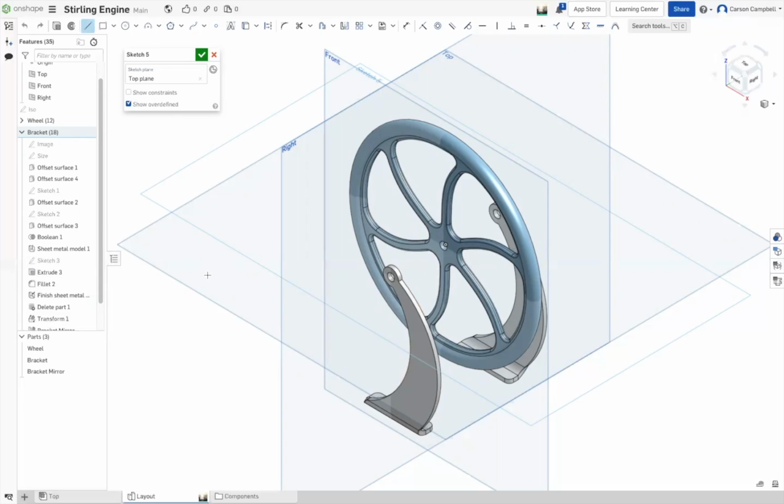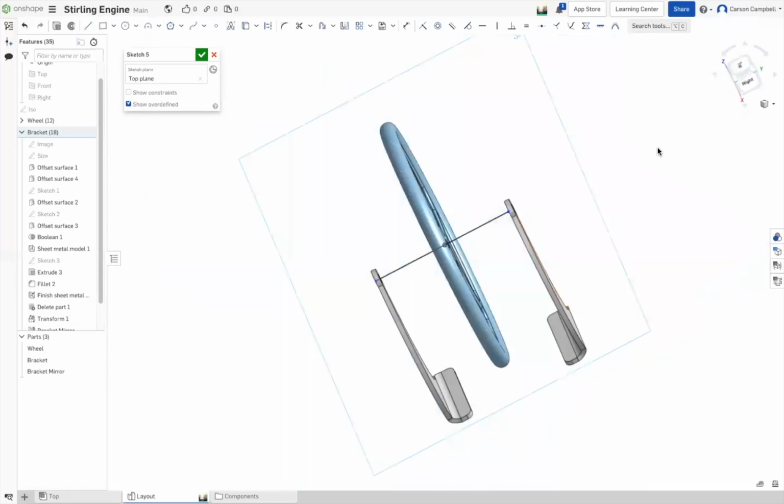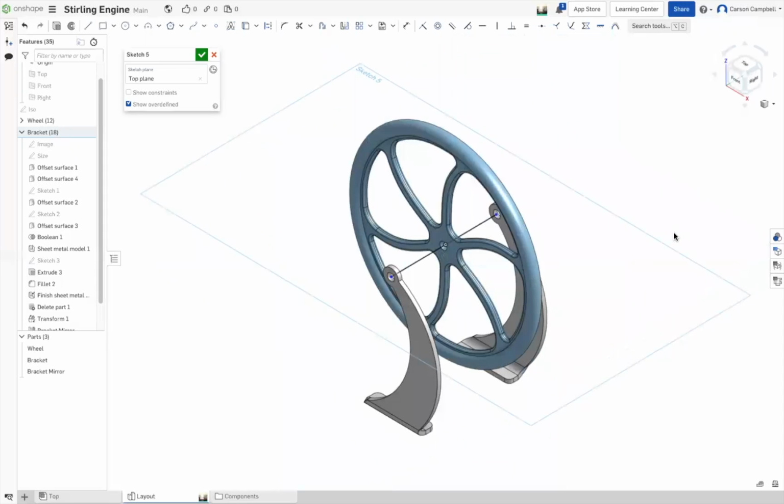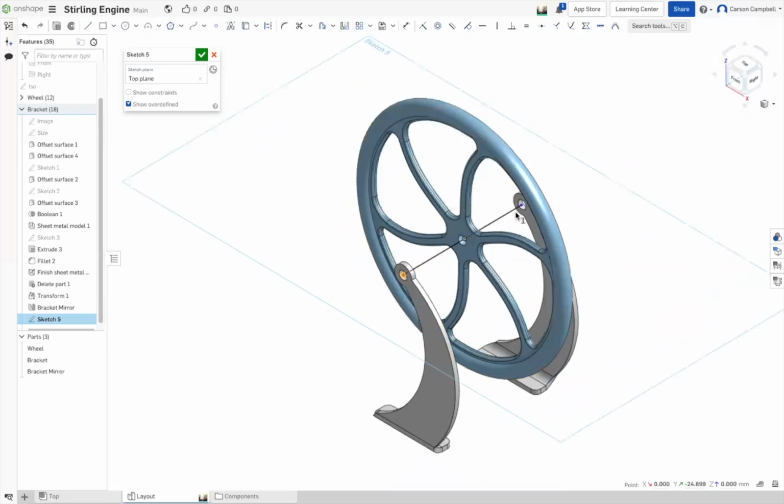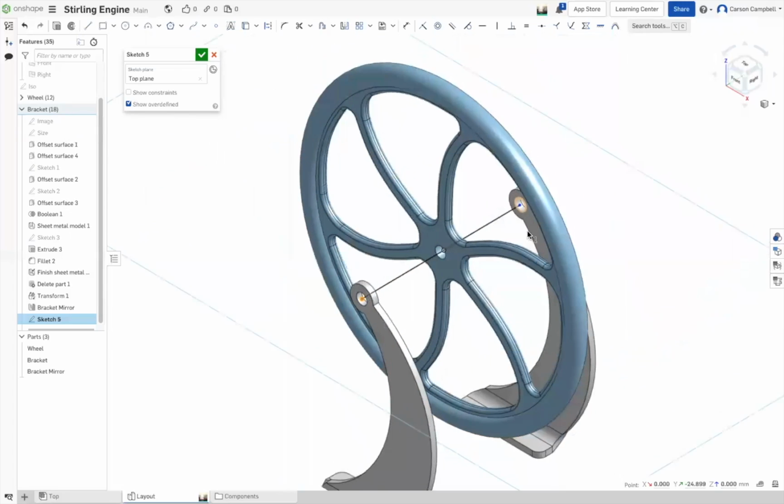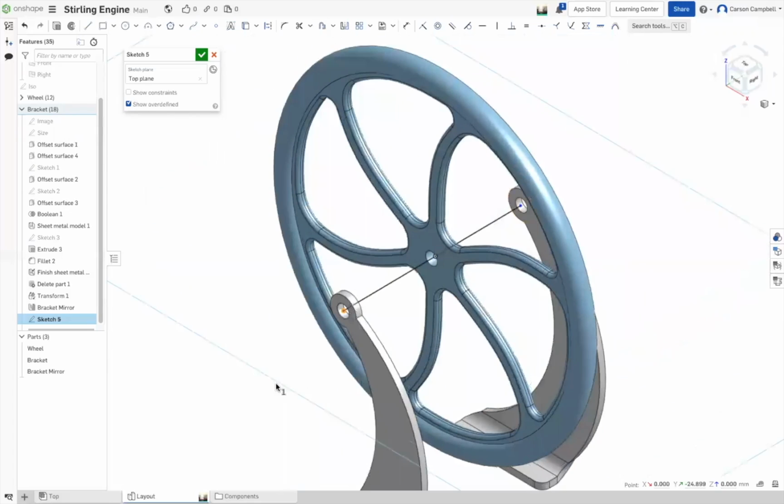So I want to create a point, just drag a point from one, yeah, and then go over to the other. Yeah, okay. Now turn your planes off. Let's add some constraints so we have the proper length. I need to go and click one of the ends of the line. And I need to pick the inside face. Not that face. You need to rotate the part.